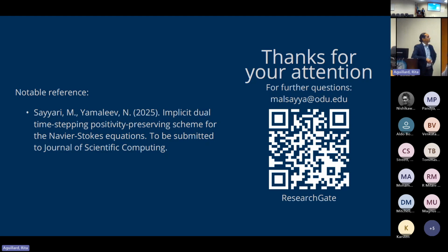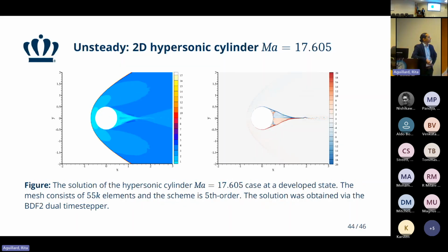It is curvilinear. I don't have the mesh here, but basically we mesh some sort of a circle around it, so we get the boundary layer, and then it expands from there. We're not interested in the region in front, but we're trying to resolve a little bit here, and we don't focus on even the tail as much. So we have open boundaries, supersonic.